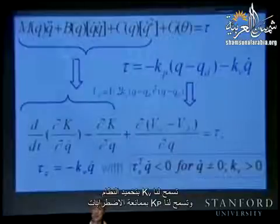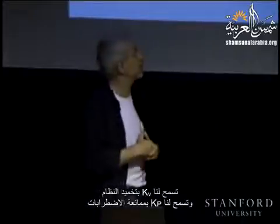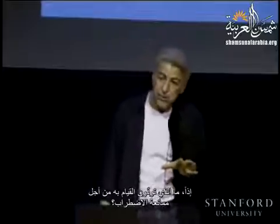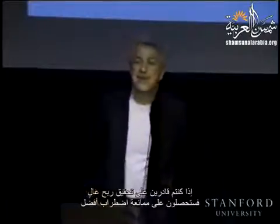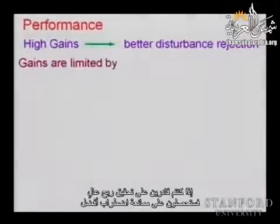The Kv allows us to dampen the system, and Kp allows us to reject disturbances. So what would you like to do in order to reject the disturbances? You want Kp as large as possible. You need high gains. If you're able to implement high gains, then you get better disturbance rejection.